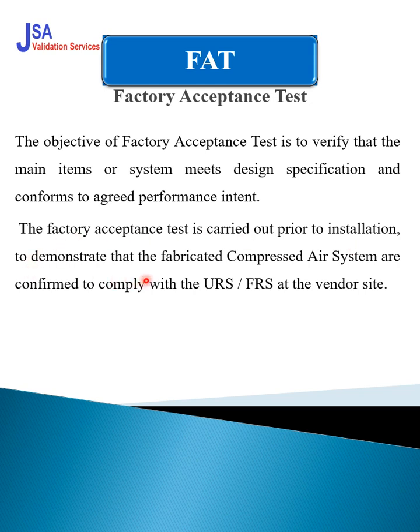It also demonstrates that the fabricated compressed air system complies with the URS and FRS at the vendor side. As I told you, this is done at the vendor side. It is mandatory for critical equipment or direct impact systems. You have to challenge the system at the vendor side. The company representative, QA, engineering, production and operator form a team and go to the vendor side with the protocol, either provided by the company or by the vendor, by mutual agreement.